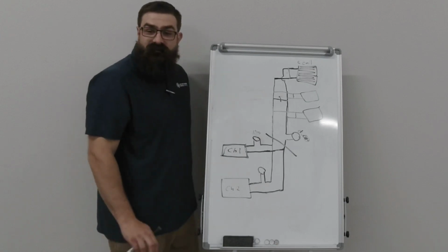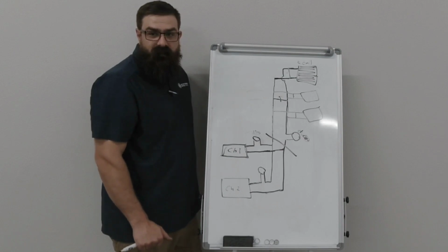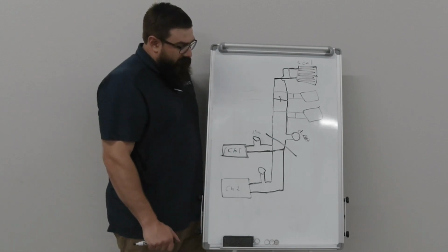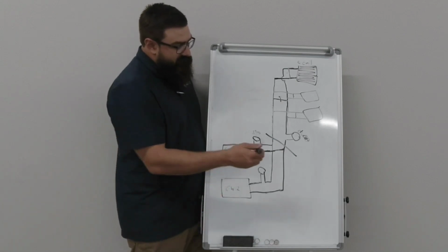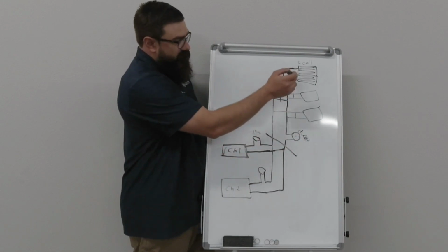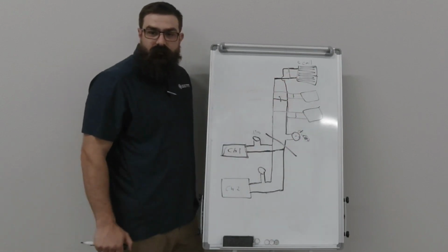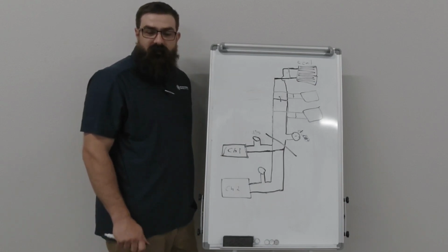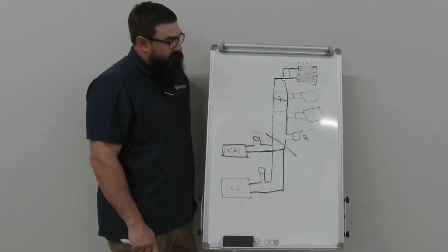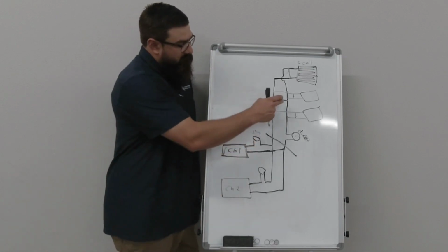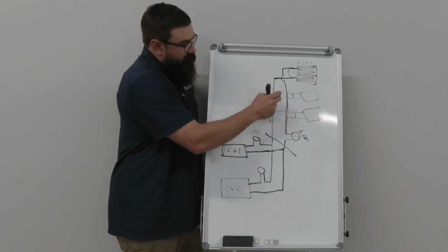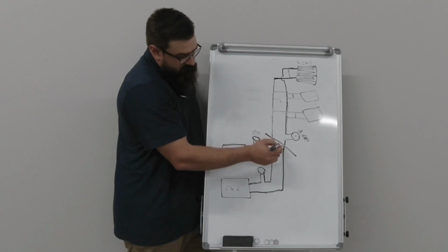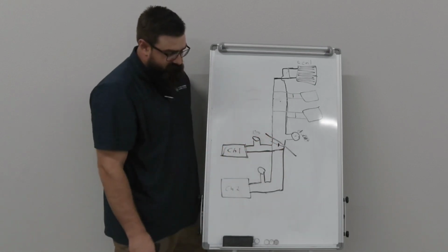It just depends on how the system was designed, and then if it's been retrofitted, somebody's changed it later on. But if a pump is constant volume, you're typically going to have all three-way valves, or at least your top one will be a three-way valve that's set to a certain amount of flow. And then, like I said, your bypass valve can either be up at the top or it can be down in the plant to help maintain the flow through the chillers.